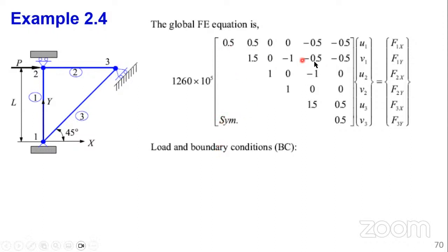Good. So apply boundary conditions. These ones are outright, the ones I was explaining at the beginning of this question: the U and V at node 1, V2 at node 2, and at node 3, V prime 3 is equal to 0. Again, we know F2x in this direction, x, is equal to P. And of course, as a result of the roller support, no reaction can develop in the axial direction. So that's why F prime 3 is equal to 0.